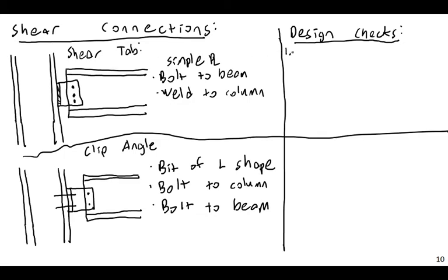Well, for shear anyway, one, in this particular case, the beam web shear capacity could fail, including its reduced capacity from having holes in it. Two, the bolts could fail in shear. Bolt shear check, I might just say.